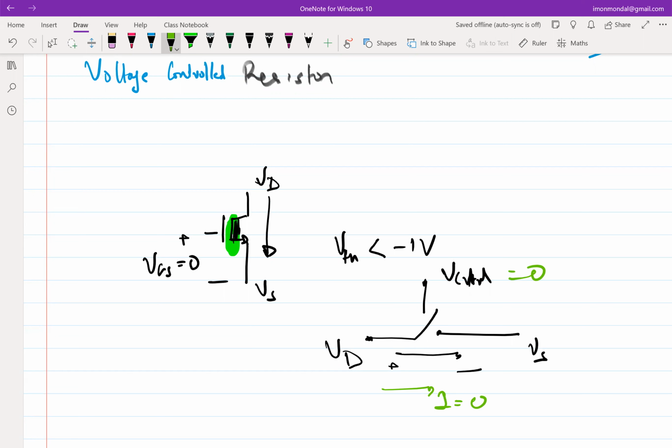It's essentially a loss. So that is why these type of MOSFETs, I think this is called depletion type MOSFET. I might be wrong in the terminology, but that type of MOSFET is not used very often in circuit design. We mostly limit ourselves to MOSFETs which have threshold voltage of greater than 0, which are called enhancement type MOSFETs. Okay. Yes. So why is this negative voltage a problem for us?